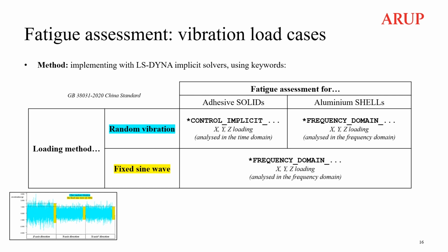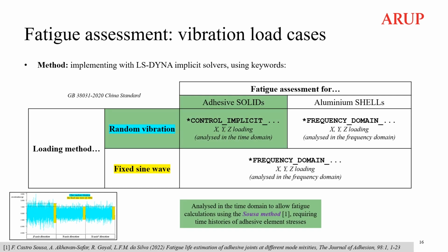The reason for analysing the adhesive in the time domain was to enable the fatigue post-processing calculations to be performed by something known as the Sousa method, which required time histories of the adhesive element stresses. The Sousa method will be explained shortly.